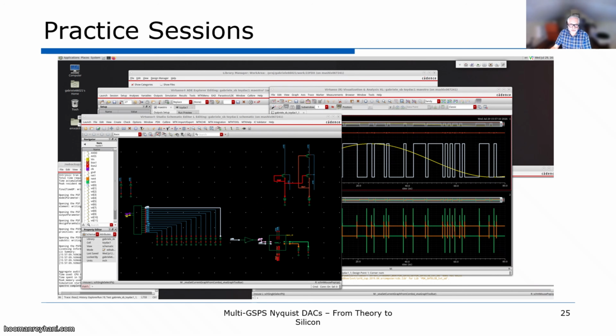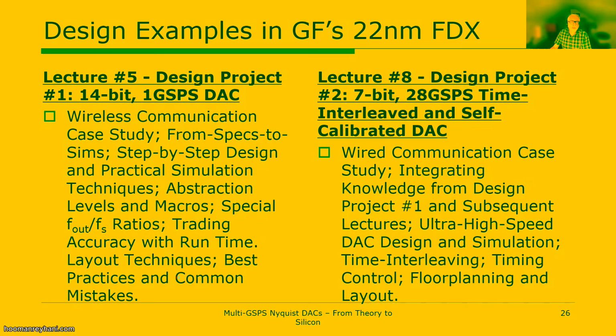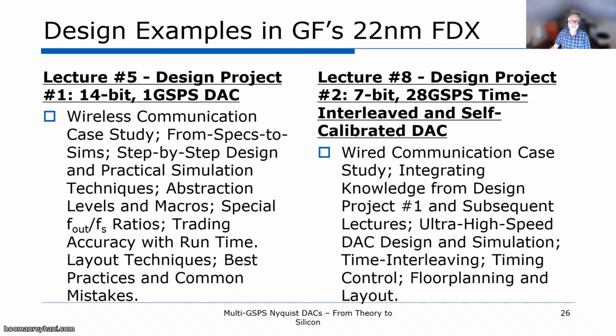To keep our practice sessions grounded and engaging, we will focus on two complementary examples using GlobalFoundries 22 nanometer FDX technology. A 14-bit 1 gigasample per second DAC that is typical for wireless applications, and a 7-bit 28 gigasample per second interleaved DAC geared toward wired communications.